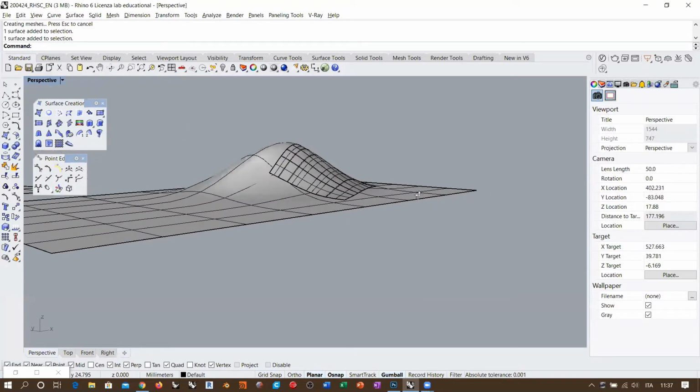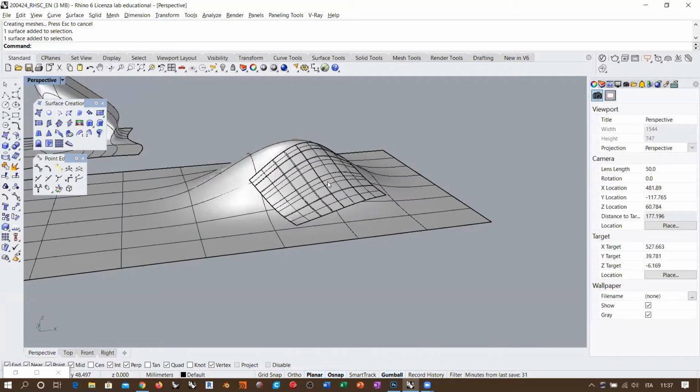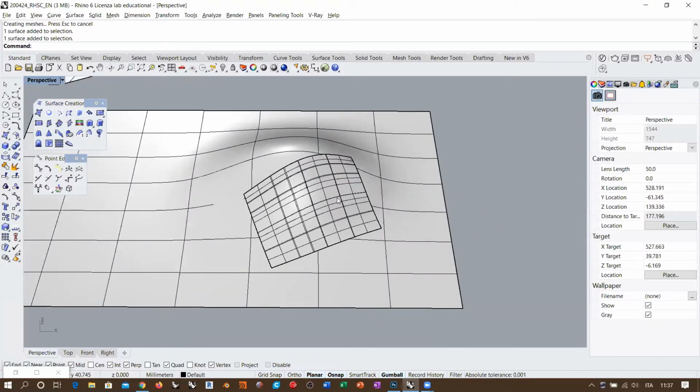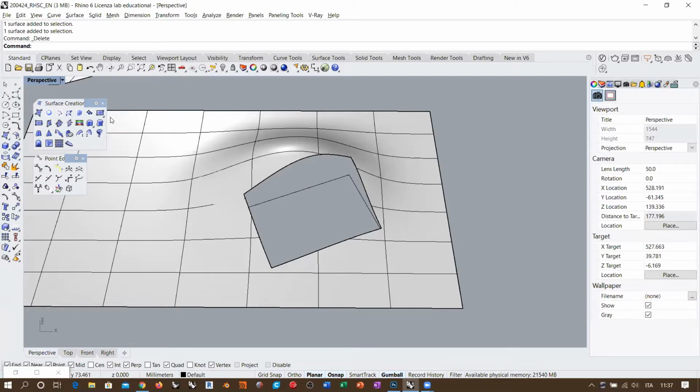So you will always have to take the 3D model and make some imagination effort to think about what would be the final result of your production process. Okay. But if you want to be extremely precise, so let's say that this is, for example, an aerodynamic surface, and you need to have it perfectly under control, then in that case, you don't want to use a command that is totally interpolated on the inside. Okay, especially because it doesn't allow taking care of the continuity along the edges.